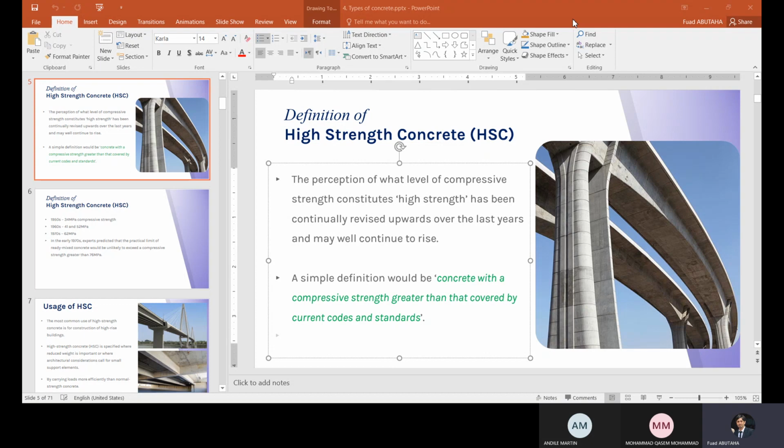So you need to memorize this one, and you need to consider this in the site when you design any mix design, in the site or anywhere. So always the smaller particle size decreases the workability. The large particle size, the biggest stone range, it can go up to 14, 15, 16. The higher particle size is the higher workability. Okay, so this is the first one.